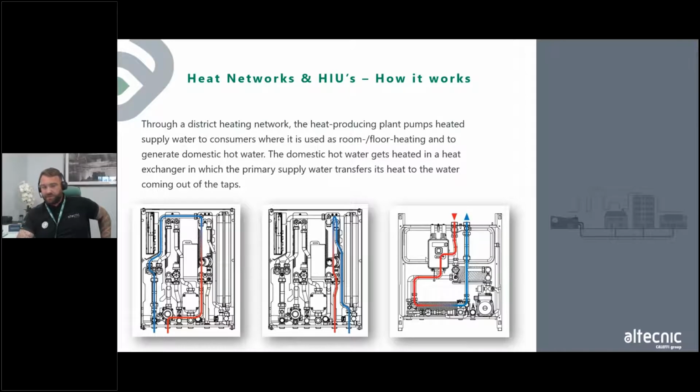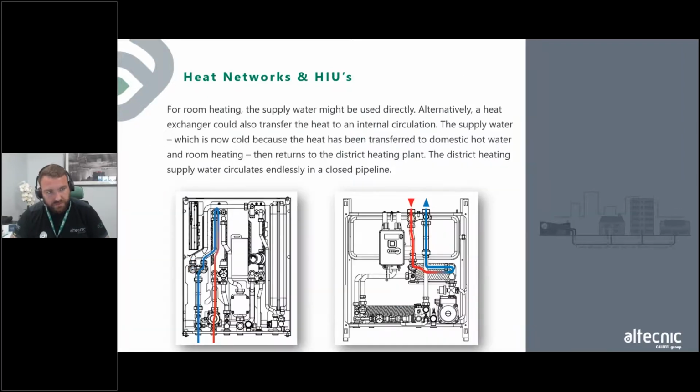They're just different configurations of HIU. One's heating, one is hot water, and the other one is a different model of HIU. I think the important thing to remember, and one thing that we will talk about shortly, is the delta T, and that's the difference in temperature of the water that's coming into the HIU and the water that's going back out of it. So delta T is something you'll hear us talk about quite a lot.